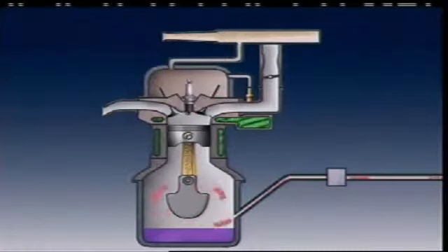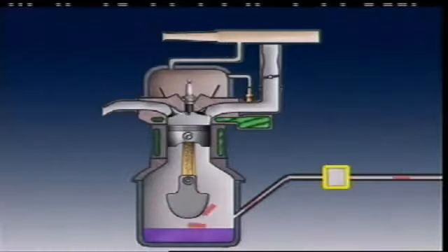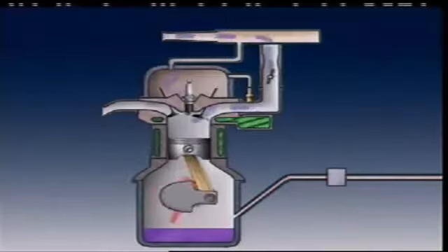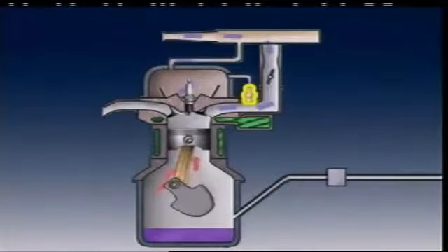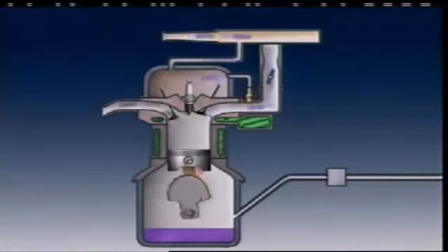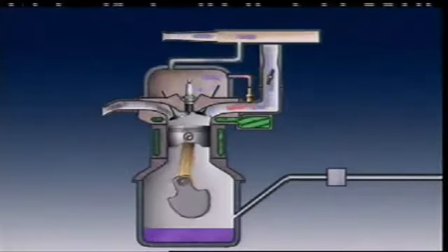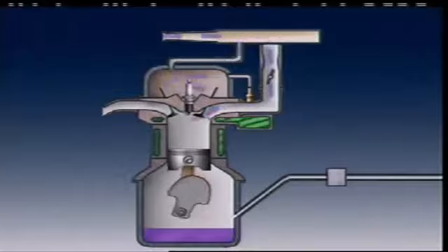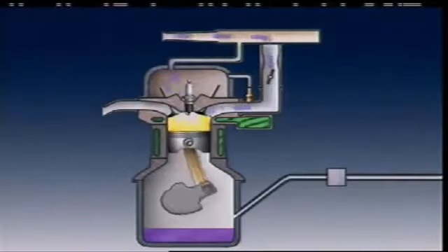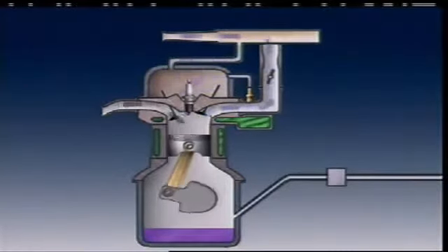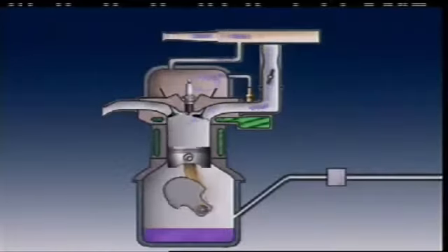When the temperature of the fuel in the tank increases, fuel vapors are forced along the vent line past the liquid check valve and into the crankcase. When the engine starts, the positive crankcase ventilation system flushes vapors out of the crankcase and into the intake manifold, where it joins with the inlet air-fuel mixture. Once in the inlet manifold, the vapors are drawn into the engine, where combustion can convert them into carbon dioxide and water vapor.